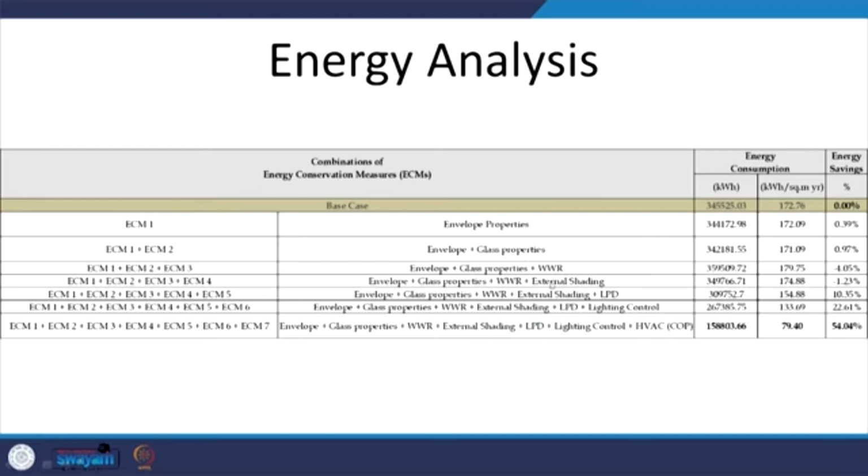If we look at this particular table, we see here that the moment we increase the window wall ratio from 40% to 60%, we see a 4% dip in energy savings, which means that this option with more windows, having added 20% WWR, consumes more energy. So, we know that higher WWR is going to result in more energy consumption.